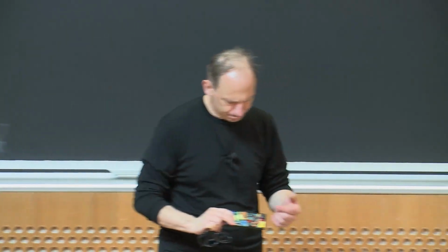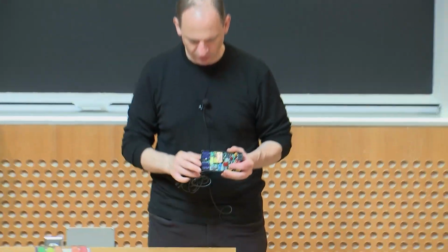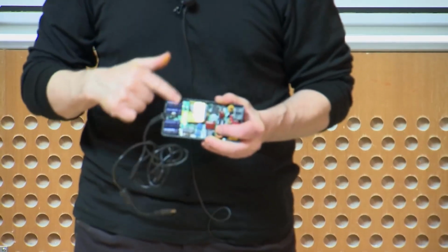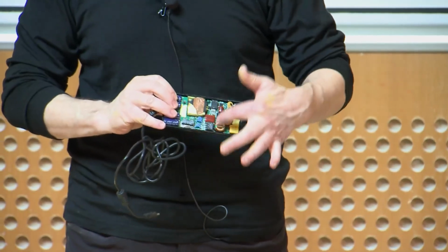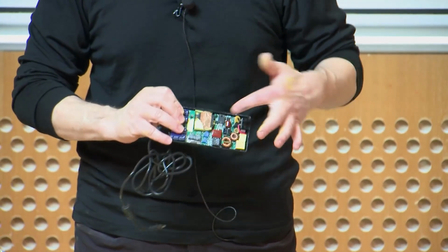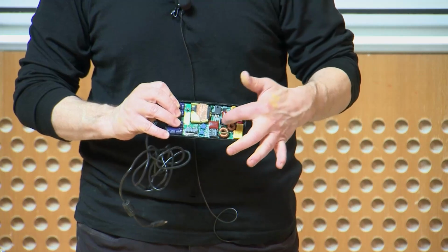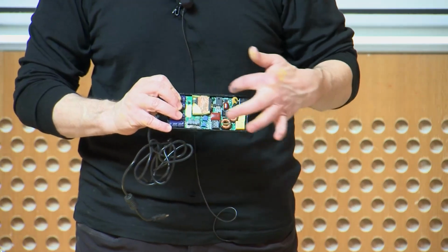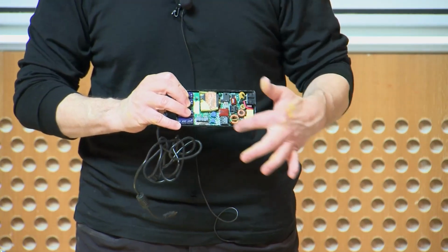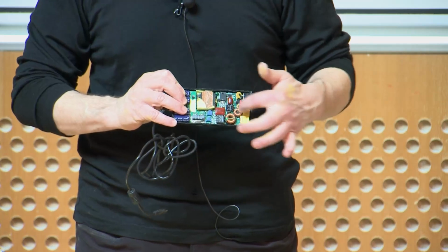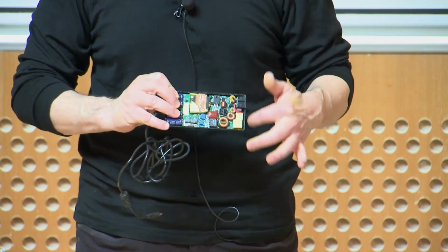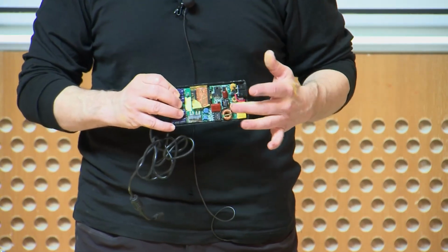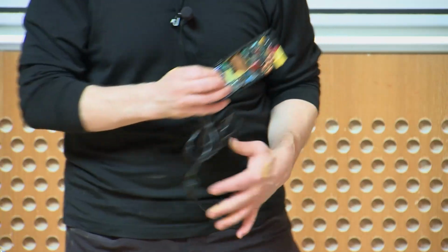If you look at this, here is the twice line frequency energy buffer over here. Here's the power stage. There's a rectifier up front. But a good chunk of this converter right over here is the EMI filter for plugging into the wall. We're going to talk about how you would structure things in a line interfaced application, but also in a bunch of other applications.